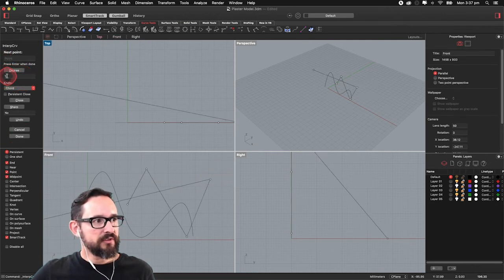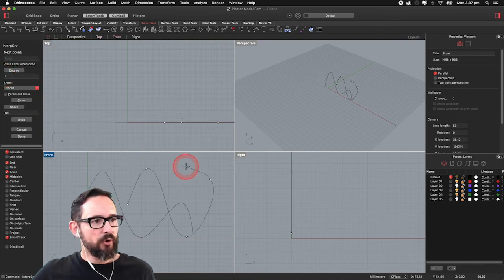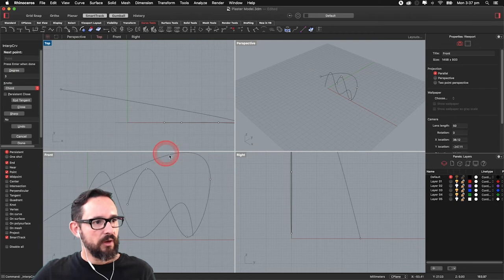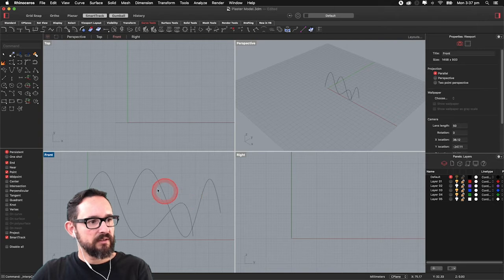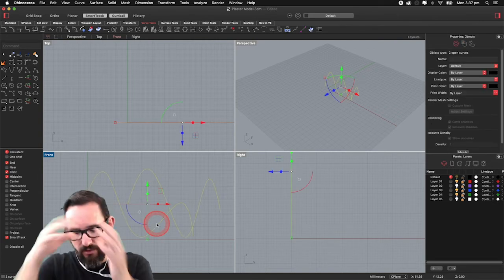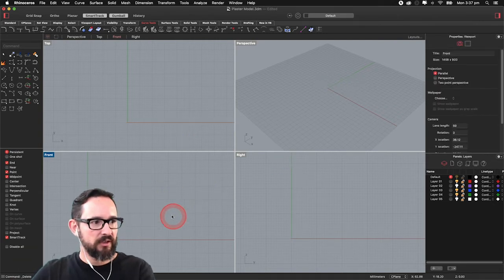If it becomes 2, it's an average point curve, and 3 is the interpolated curve through points. So basically, that's the difference, right? In this case, we are using 3 because we want that curved element, so the degree is 3, and you saw that already in the rebuild before.